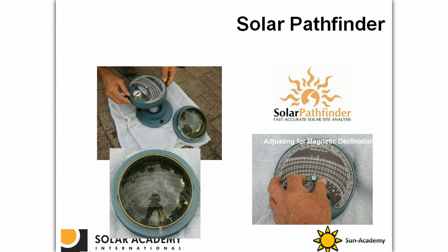One of the tools is a solar pathfinder, which determines the shading in any location. Solar shading calculators require orientating due south depending on the hemisphere you are in, leveling and locating at the appropriate solar system height prior to making shading measurements.